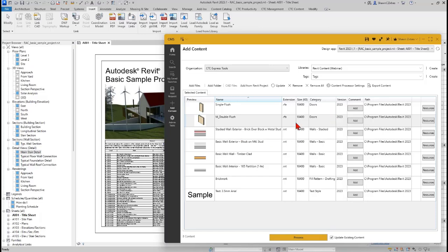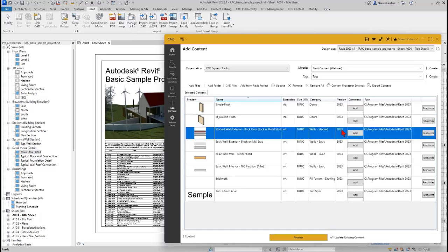Earlier, I had mentioned component families. If you just drag and drop a component family from Windows in, it's going to use whatever version it was and upload the original Revit family. Well, this is editing the family out of the project to be able to process it, so it will be in the version that you actively have open. 100% the active version of Revit. That's true also of the system families. It has to pull them out of this active version.